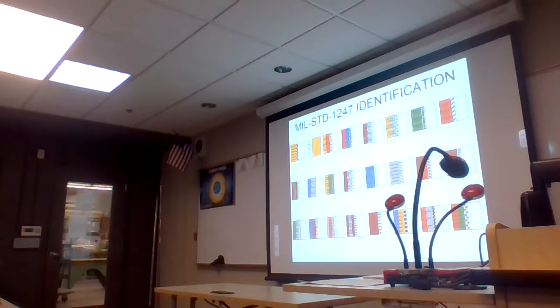In the case of pneumatic systems, they've got what looks like a series of diamonds that are interconnected, black diamonds on a white background. They use a reddish and blue color code for pneumatic systems. You'll see there's other things too. For lubricating oil, they'll use interconnected rectangles, yellow for the color code for the word lubrication. For fuel, they use diamonds. So they use diamonds. We use the word fuel in kind of a reddish brown color for it. But everything is generally identified by those three different methods of identification.